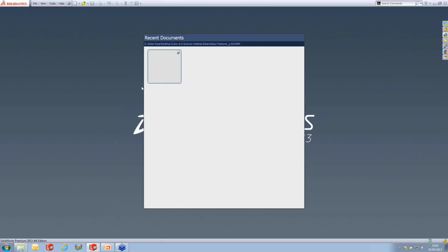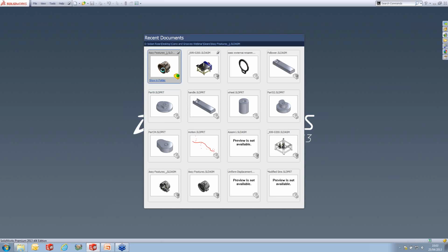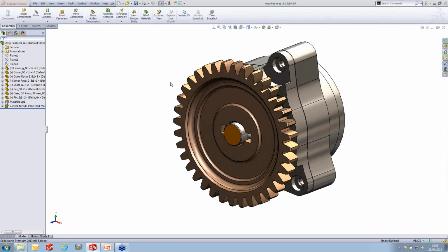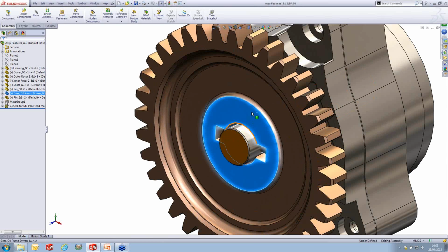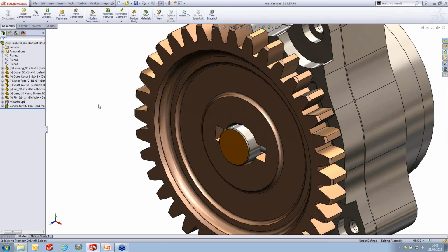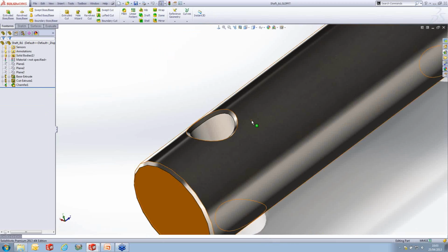What I'm going to do first of all is have a look at the grooves tool. So I'm going to switch over and open up a recent document. Now this assembly file, I want to put on a retaining ring on this end face in order to hold this mechanism in place. So what I'm going to do is to open up this part, because you have to open up the part in order to insert the cuts for the retaining rings. You can't do it at assembly level, for example, by editing the component. So we've got to make sure it's open in its own window.